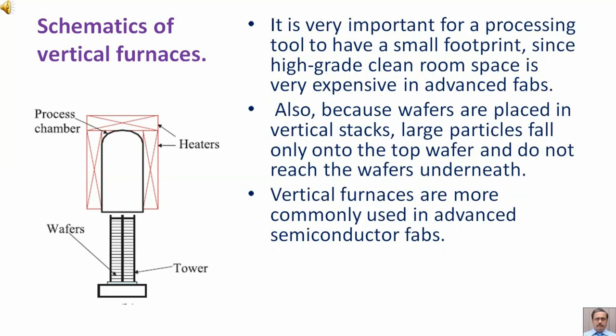It is very important for a processing tool to have a small footprint, since high-grade clean room space is very expensive in advanced fabs. Also, because wafers are placed in vertical stacks, large particles fall only onto the top wafer and do not reach the wafers underneath. Vertical furnaces are more commonly used in advanced semiconductor fabs.